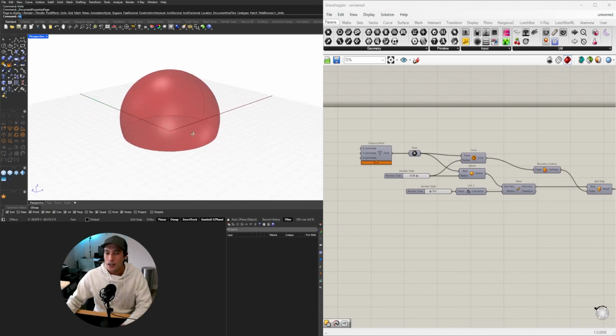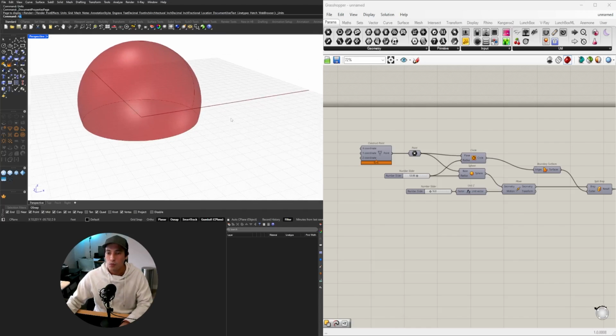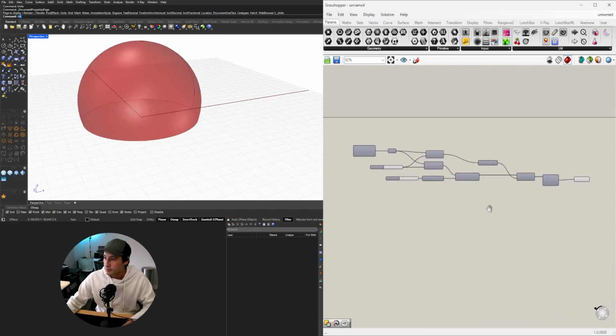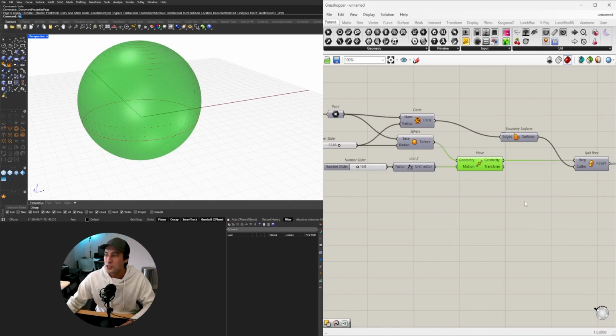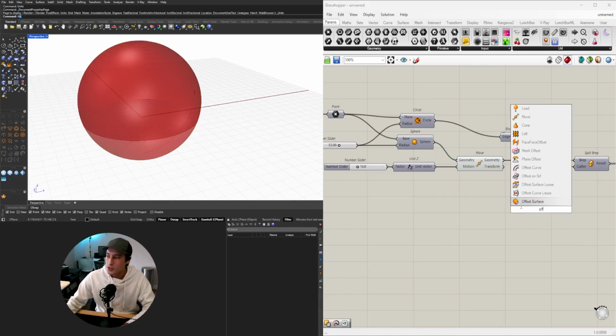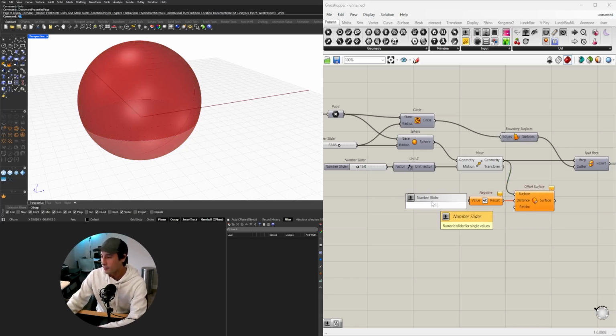And now we can hollow out the sphere so you can have some space within and have some wall thickness. To do that, we can do it two different ways. We know we have the sphere, which is the exact same size as the outside. Now, if we took the sphere and we offset the surface to the inside, so if we went in a negative direction, we offset this by, let's say, 1.5.